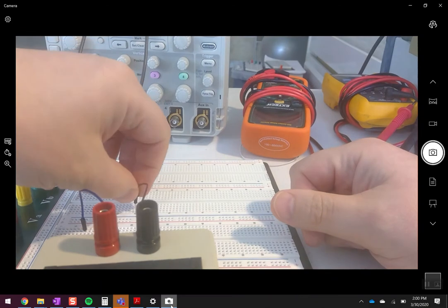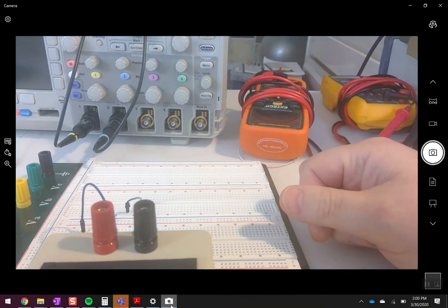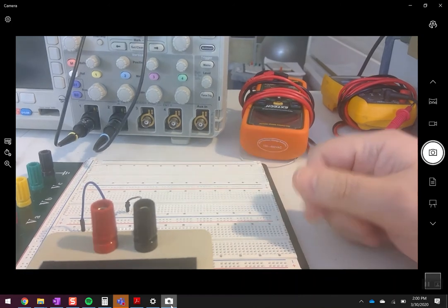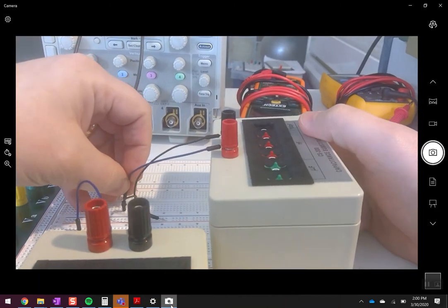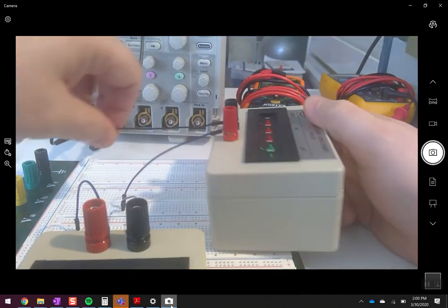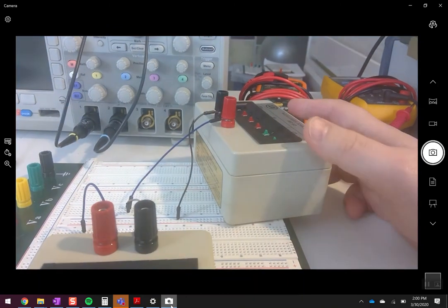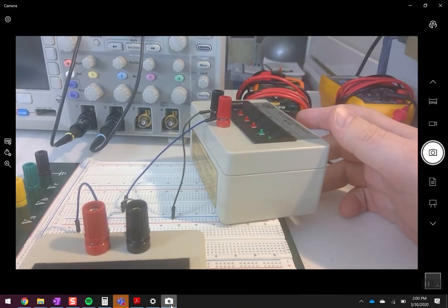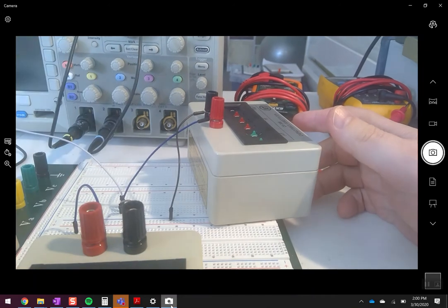And then I'll put one of the black ones here, so that's where the capacitor that goes to ground is going to connect, which is my 1 nanofarad capacitor. I'll just use this rail here for ground.